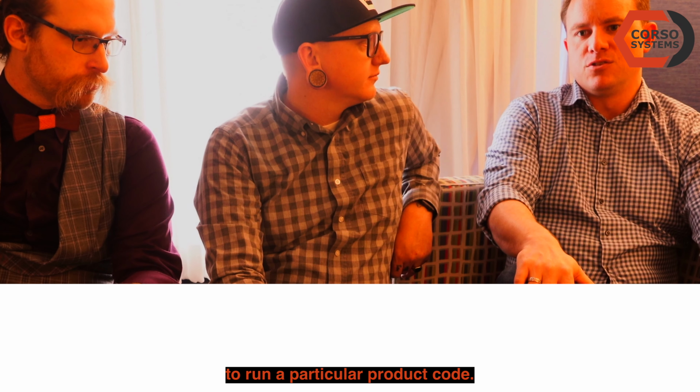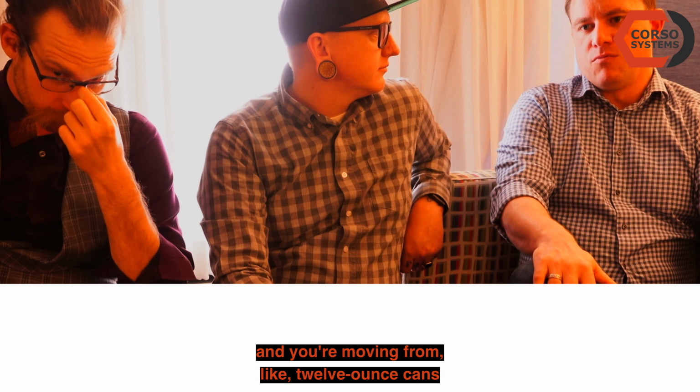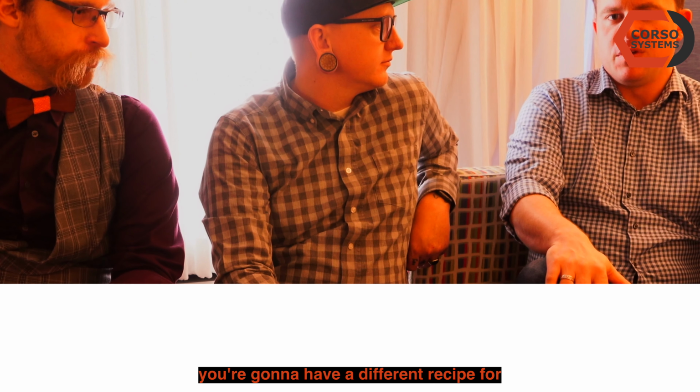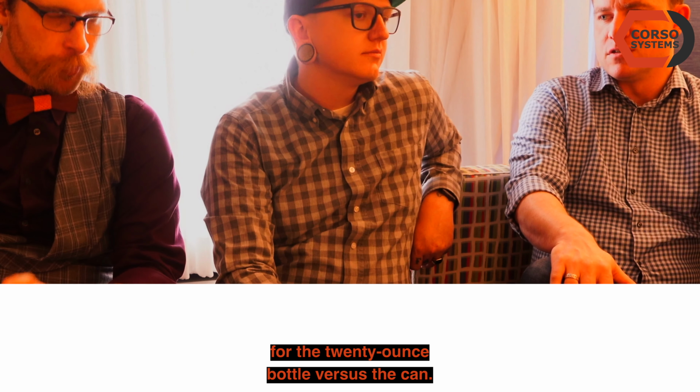a particular product code. So if you're in a food and beverage plant and you're moving from like 12-ounce cans to 20-ounce bottles of soda, you're going to have a different recipe for what your fill set point needs to be for the 20-ounce bottle versus the can.